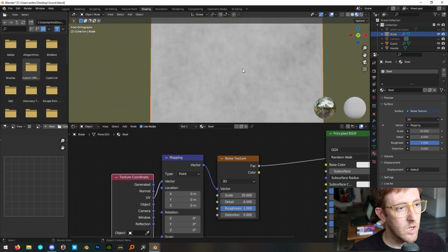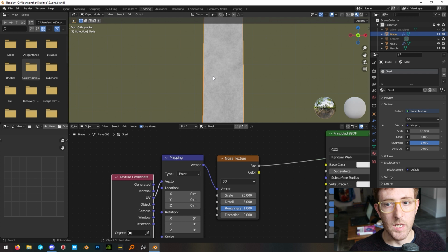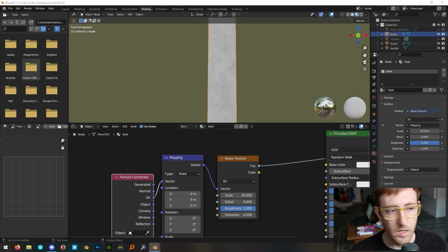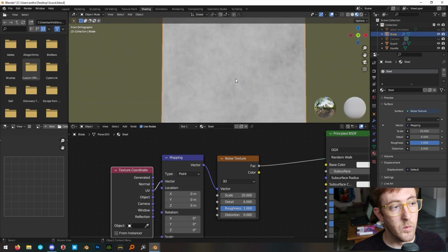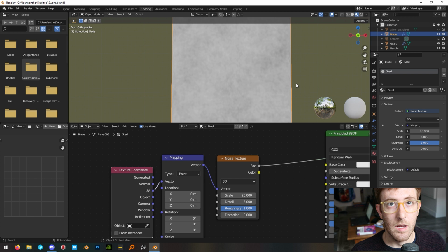And so you can see that we've got this noisy texture on the surface of our object, and now what we want to do is use that to drive the roughness. Now what's coming out of this channel is white and then dark gray. But because this is metal, we want this pattern, but we want the range of values to be more from very dark gray to less dark gray. The reason is that that's what's going to determine how rough the surface is.